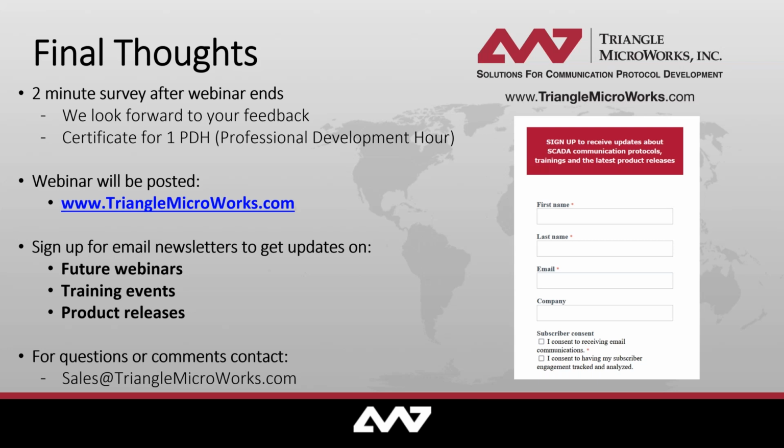But once you have those messages, the single line canvas that I showed really is more of a generic HMI tool, or at least a visualization tool, and it is just a single line tool. You do have the ability to bring over a number element like you would have on a typical HMI, and you could link that to anything, including a sampled value measurement or something that's coming in via report periodically instead of multiple times per second, and that value could be updated.